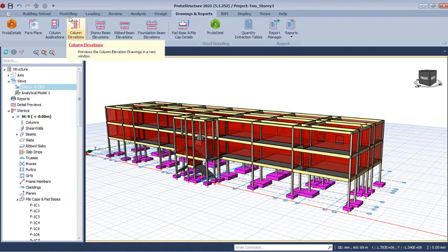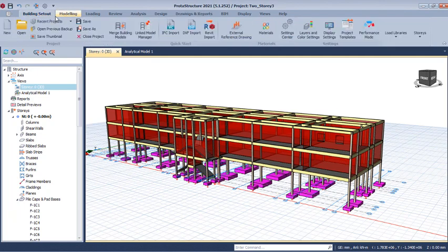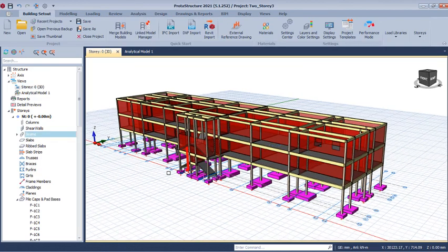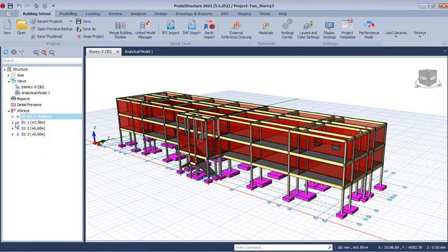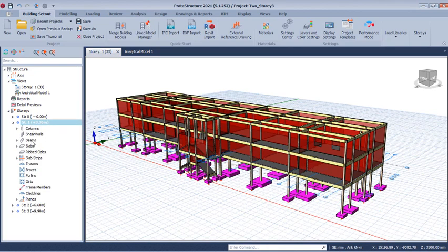You will have to navigate to the setting out, and then we need to select the beams. Let's say we'll start from the first floor beams to do the interactive design. So I will navigate to story one, which is the first floor beam, this one, right click, and then I will click on RC beam design at story. So this will give me the beams of the first floor only in a dialog.